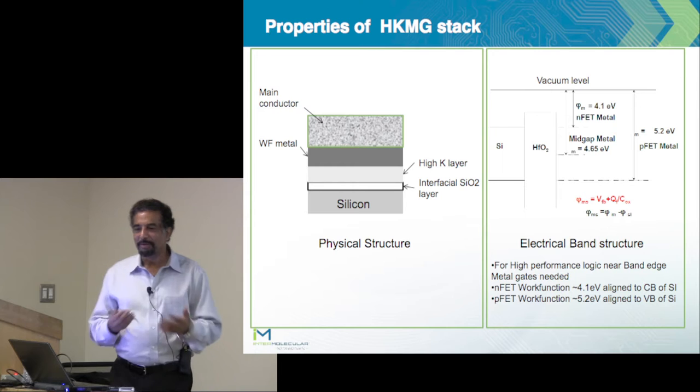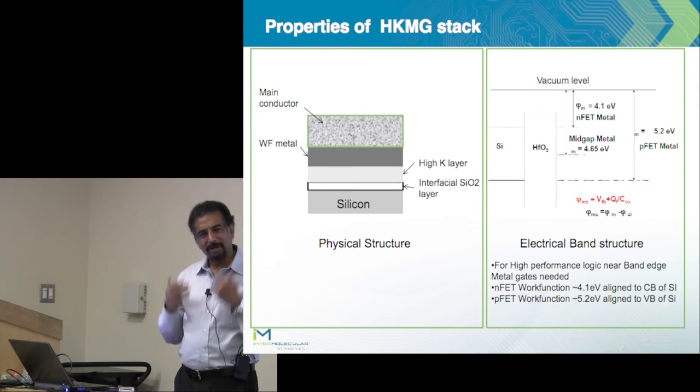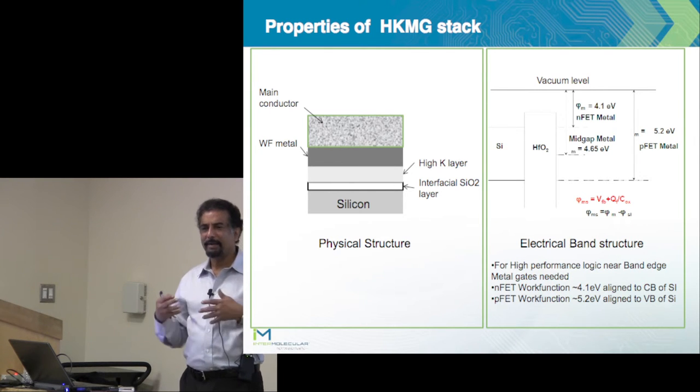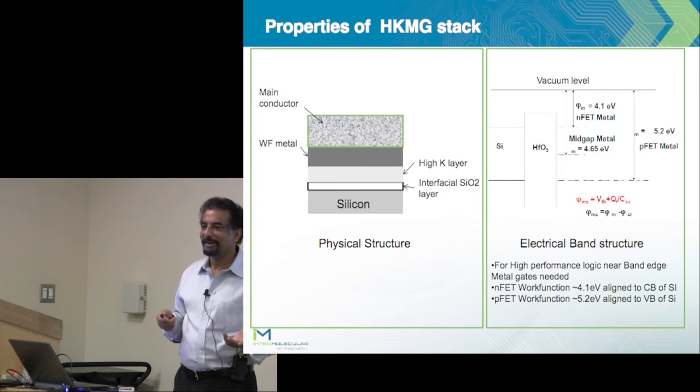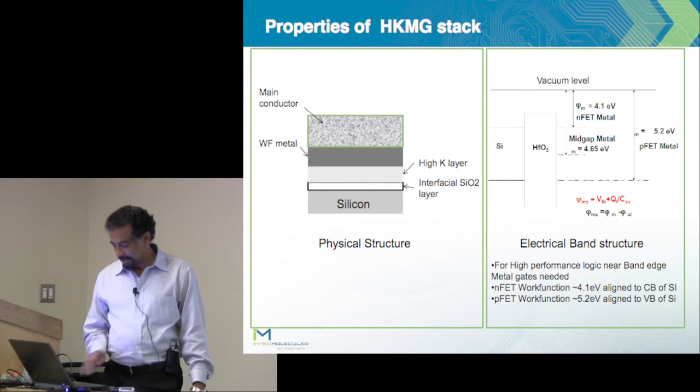Again, if somebody came and told me, I put in 8 angstroms, I put in the hafnium oxide, I'm quite sure I still had 8 angstroms of oxide, and yet after I put the metal gate on and went through anneal and came back, that 8 angstroms became 20 angstroms, right? And I would ask, what's the driving force and what's the kinetics of that? We'll get to that.